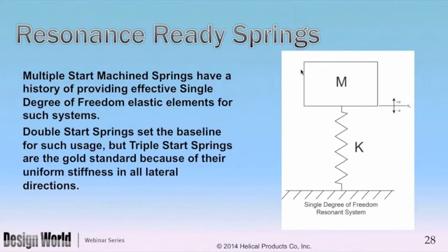The thing will rock back and forth, and you'll have guides, you'll have rubbing surfaces, and it becomes a problem for any single degree of freedom spring or single start spring. But in a double start spring, remember the moments are resolved, and this thing will literally move up and down with very little lateral activity.